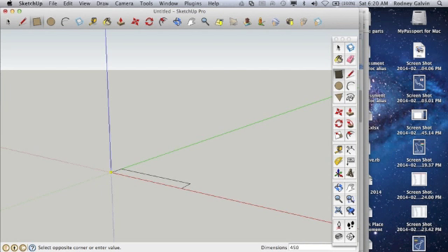So I'm going to start with one, and I know my cutting board needs to be 450 millimeters long, so I'm going to type in 450. You'll notice down the bottom that the size goes in. I'm going to start my first piece to be 40 millimeters wide, and once I've typed it in, if I press enter, the shape comes up.